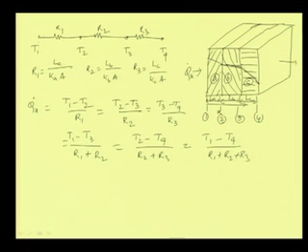Current flow is there, so the drop in temperature from one place to another depends on it. Here we have very high resistance, here the resistance is very less, and here the resistance is moderate. This way we can find the temperature profile at different points in a composite wall.